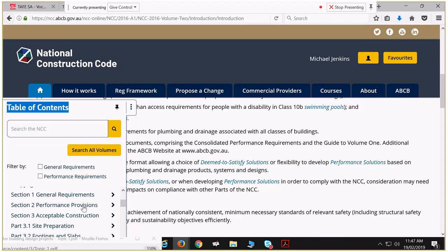The National Construction Code defines the way in which we build by two methods. One method is it says that, let's say, a class 1 building should be this. It should stop water getting inside of it, right? It says that it has to be not watertight, but resist the passage of water into internal outlets. So it says that's how it has to perform. That's called the performance solutions.